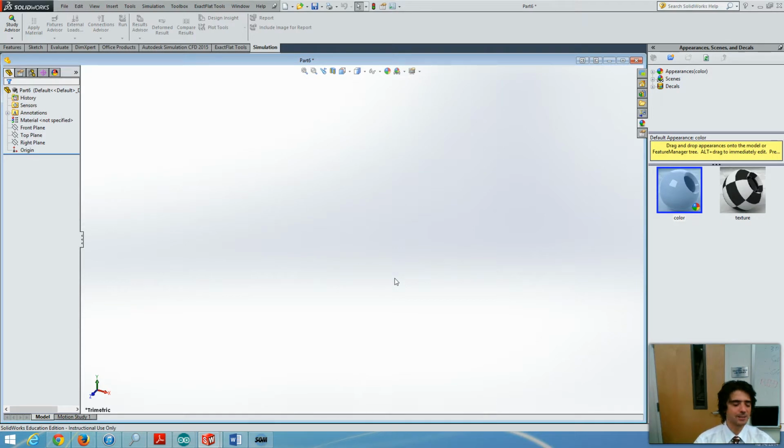In this exercise, we are going to experiment to measure the sectional properties of a cross-section. The cross-section we are going to create consists of a parabolic portion, so you will also learn a new sketch command for making a parabola. This is from Vector Mechanics for Engineers, problem P5.11. The coordinate system is originated in the center, so we are going to make the parabola vertex 3 meters high and 4 meters half width of the parabola.